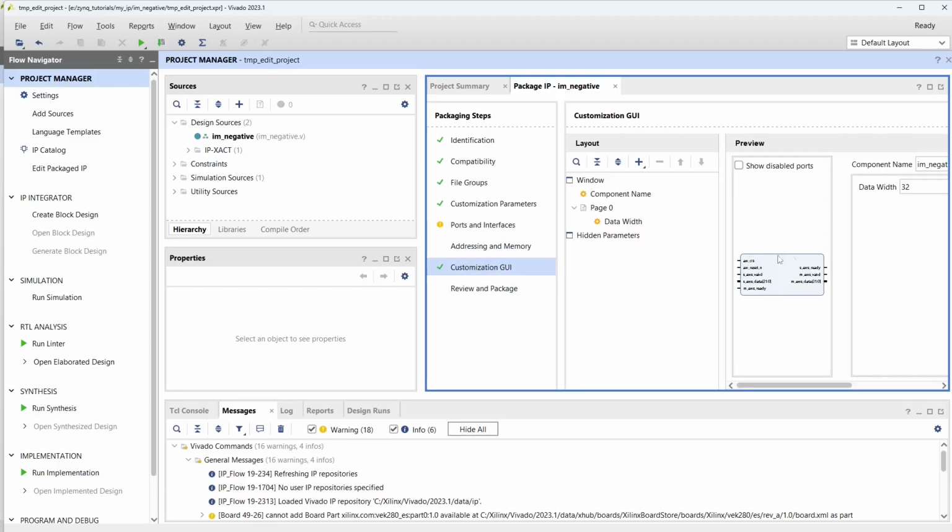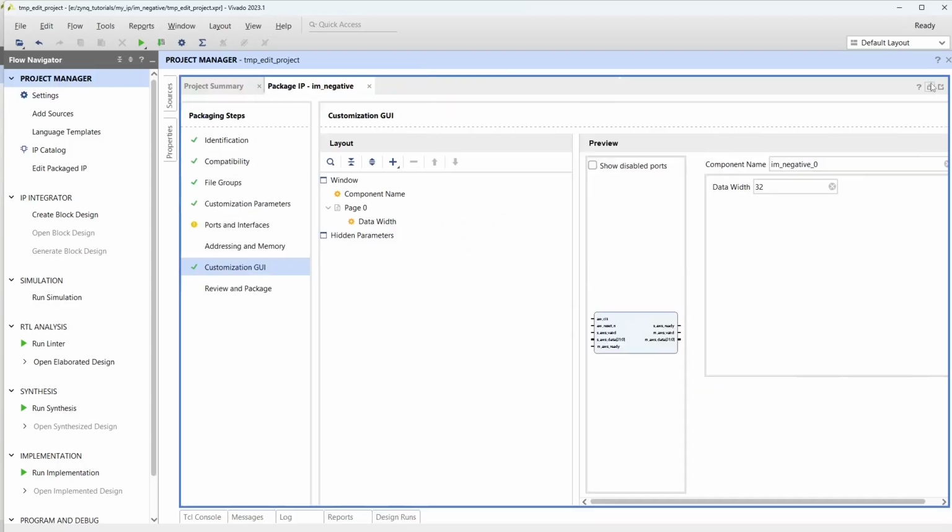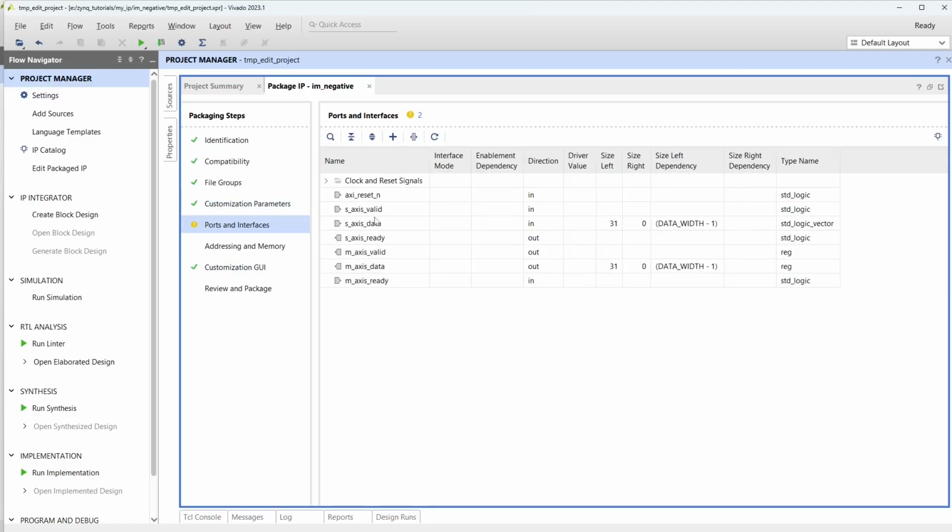So if you look at the GUI, just maximize it. You will have some GUI here. This is the GUI for your particular module. You can see all inputs are on the left side and all outputs are on the right side. This is how it organizes. But when you add some IP block, you can see that it's not like that. It is usually grouped. Your slave interfaces and master interfaces are grouped. So you can do that port mapping or grouping here. You go to here, you can see the tool has already identified the clock here. Rest of the things you can do like this.